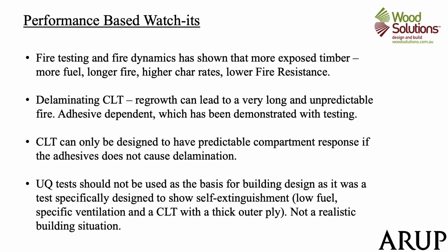Delaminating CLT can lead to regrowth, which is unpredictable and again can lead to higher fire resistance requirements. It's very adhesive dependent, which has been demonstrated by a number of tests. CLT can only really be designed predictably if it's been shown to not delaminate, so using high temperature glues. Otherwise you have to think of some ways to minimize that unpredictability. And as we've touched on, the current UQ tests are not to be used as a basis for building design, as they're not really a realistic situation, and they'll be the first to admit that.